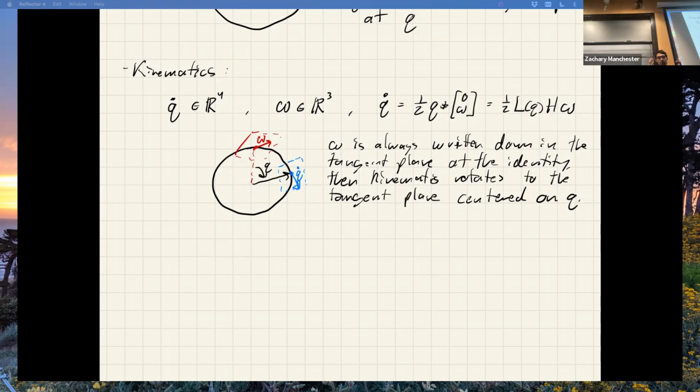sphere. So the way to think about it in your brain is the underlying geometry is this sphere picture. Euler angles are latitude and longitude. Latitude and longitude on the Earth has singularities at the poles and stuff. Euler angles have singularities at pitch equals 90 and stuff like this, right? Same thing. And just like you could write down a position on the Earth as a 3 vector with a norm constraint to make it on the surface of the Earth, that's all we're doing here. 4 vector with a unit norm constraint. Hopefully that gives you some more.